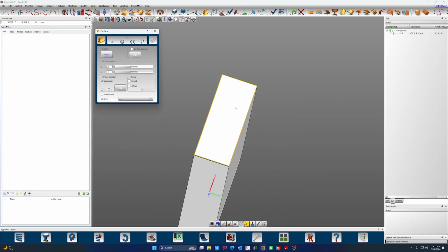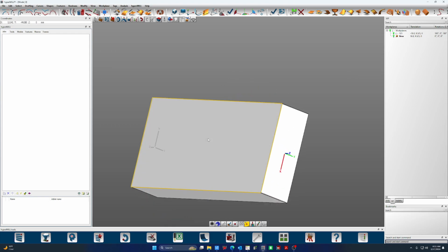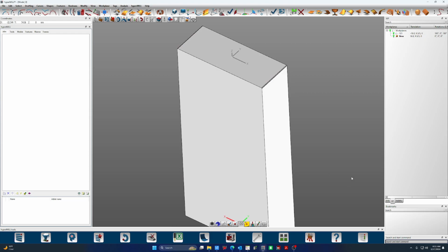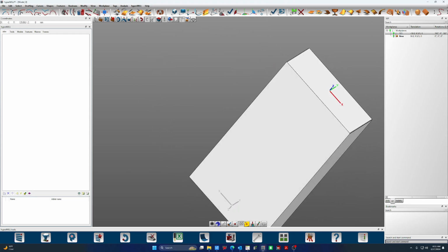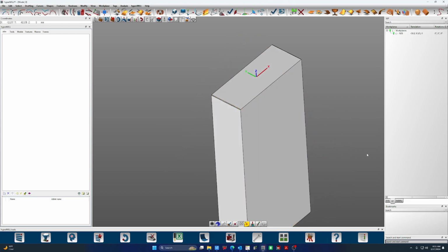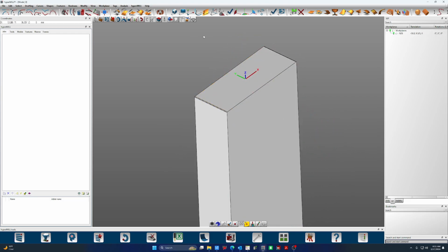So as soon as I generate another work plane on this side, you're going to see this gray phantom. This work plane exists forever now over here. And I can turn it off, I can turn it on, I can double click it to reselect it, reactivate it. Those functions you're going to memorize because they are so important.